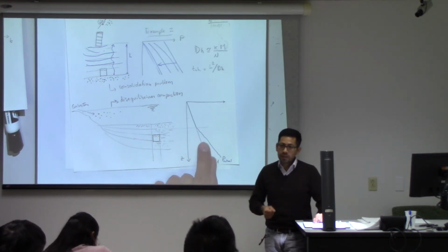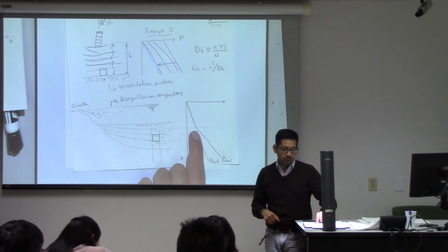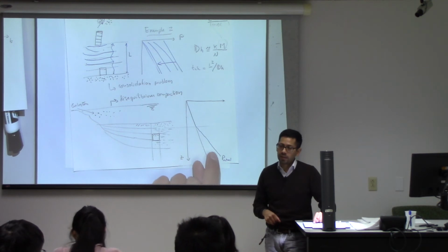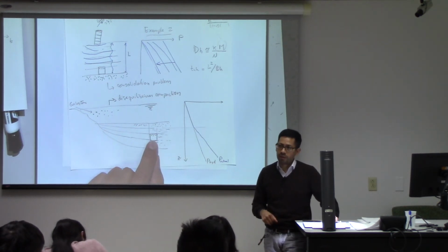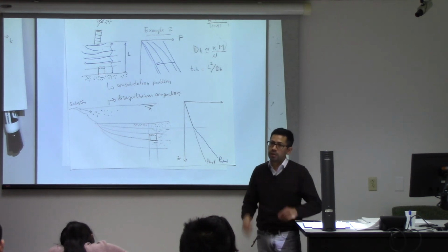So in many sedimentary basins, especially in Gulf of Mexico, there is a lot of this. You have these variations of pore pressure in which the pore pressure is not hydrostatic, but it is higher than hydrostatic because the sediment has suffered, and it is today suffering still, undrained loading, and the pressure is dissipating very slowly with time.